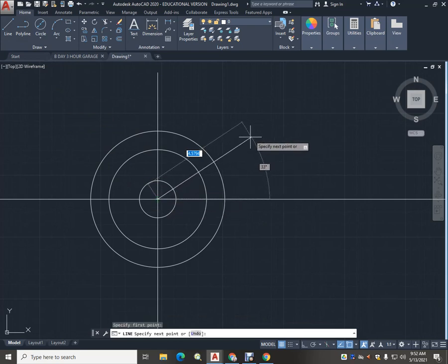Now remember that we have the ability to put a line in both at a distance and angle. Since this is just a construction line, I'm not so concerned with distance, as long as it crosses this guy, just put it out here at any distance. I'm definitely going to hit that tab key though, so I can lock it down at that 30-degree mark.